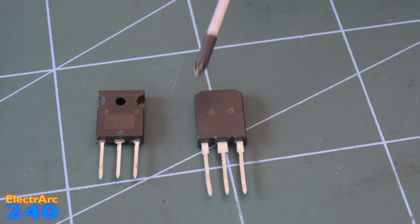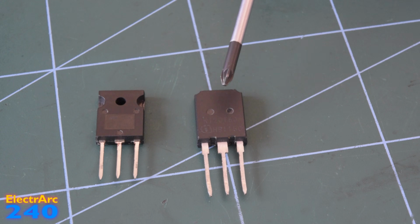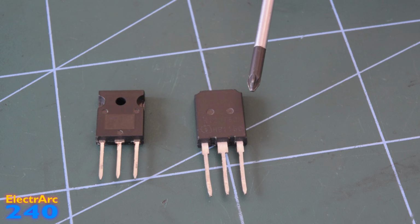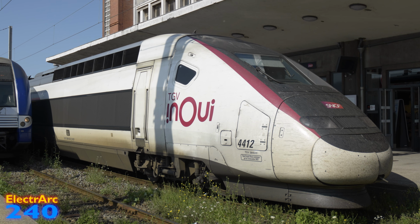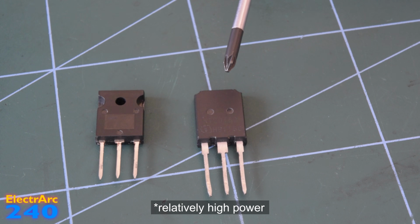And IGBTs are very common in anything high voltage, really. Most electric cars are still on IGBT, with a few moving to silicon carbide MOSFETs in recent years. Electric trains use very beefy IGBT power modules, and really, despite advancements in silicon carbide MOSFETs, the low cost of IGBTs, combined with their high voltage and current capabilities, mean they remain the king of high power applications.